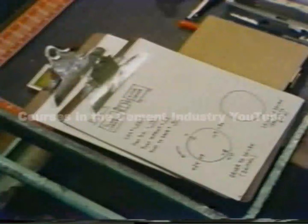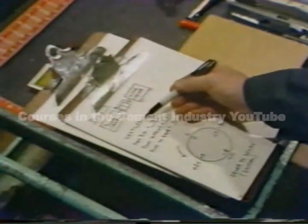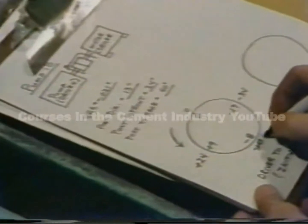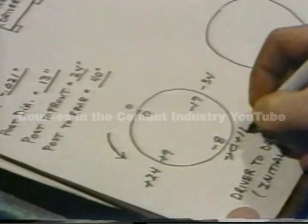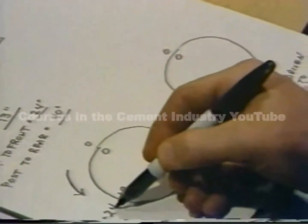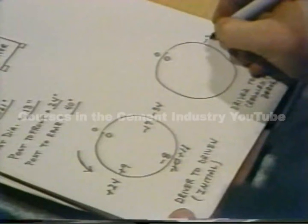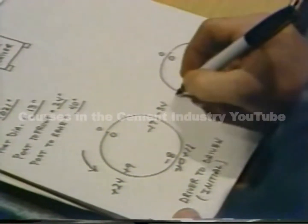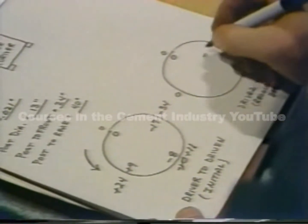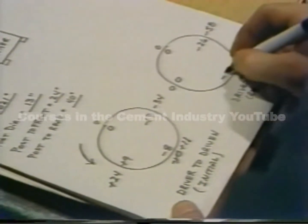This is the technician's data sheet with all the measurements and recordings he's made up to this point. The first step will be to subtract the sag from the bottom parallel reading. Negative 10 minus a negative 21 equals a positive 11. Next, he converts the side-to-side readings to zeros and comes up with a negative 58. The negative sign was the sign of the 34, so it's used. The angular readings end up at negative 26. And the bottom readings remain the same since the top started at 0.